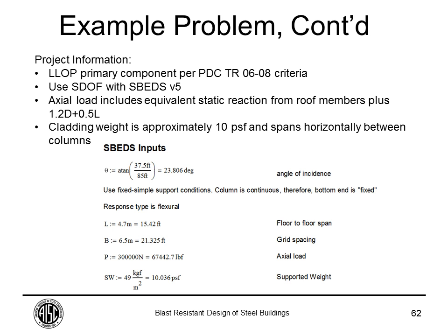We have a few questions on this example related to the axial load that you're applying. The first question is, does this include the blast load on the roof? In the example, the axial load should include the blast reaction from the components. So it should include the blast load on the roof. In this case, we applied the equivalent static reaction from the member, and also added the gravity load that was acting on the roof. That's what the assumption was in the example. Okay, great. So this P here includes the dead load, the live load from the roof, as well as the blast load. Correct.